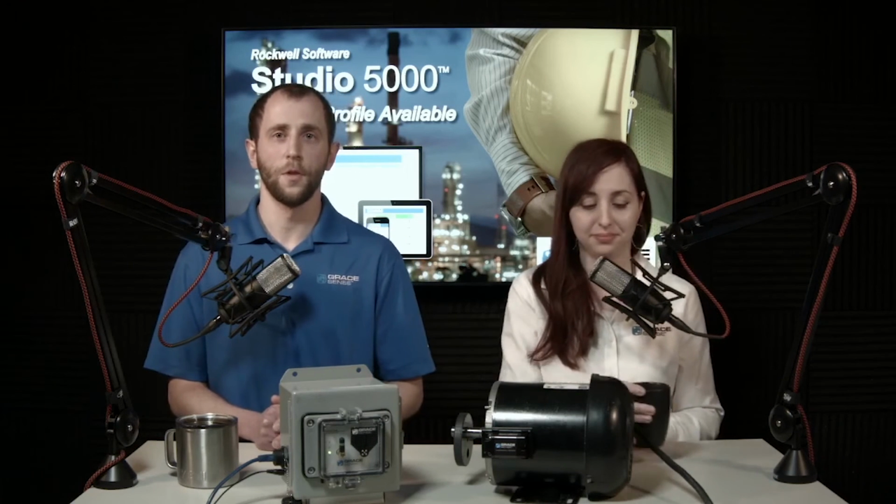So I think this was asked during the Studio 5000 demonstration. The question is, can we do the same with TIA for Siemens? Yeah, it's a good question. The only really tight-knit integration we have is currently with Rockwell and Studio 5000 using EtherNet/IP. We do have Modbus TCP as an option, so you could do a Modbus integration and then would have to do your register mapping from there. We are looking for customers who do have those applications that we could maybe build something with in those systems, so we can better support customers moving forward, but it does not exist at this time.